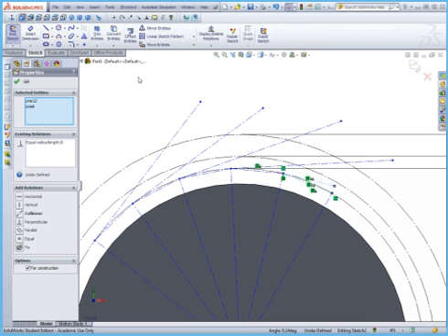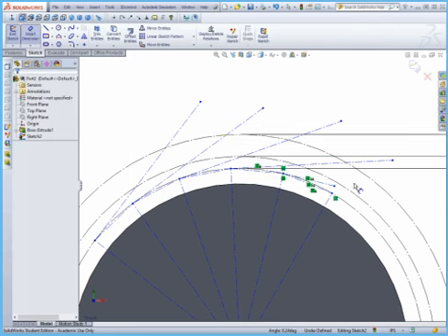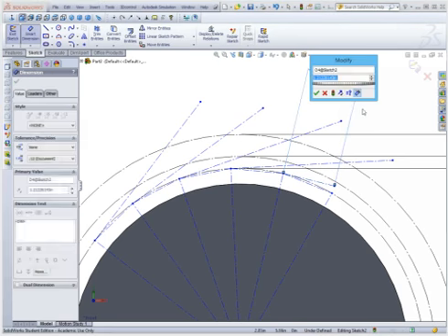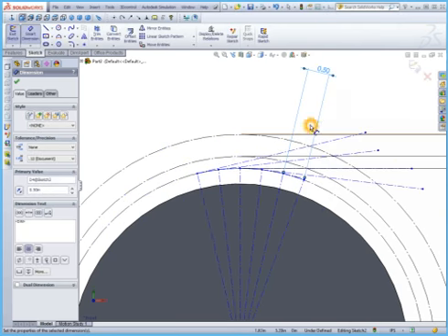So to do a relative dimension, we have to specify one of them. So I'm going to specify this dimension here, and make sure that you do the actual line dimension, not the distance in the x direction. So we'll make sure those lines are snapped correctly. And now the actual value here doesn't matter so much at first. You're going to see later on that we can change this, but I'm just going to set this to an arbitrary value. We'll make this 0.5 inches for now. And you can see that kind of brought everything in together.